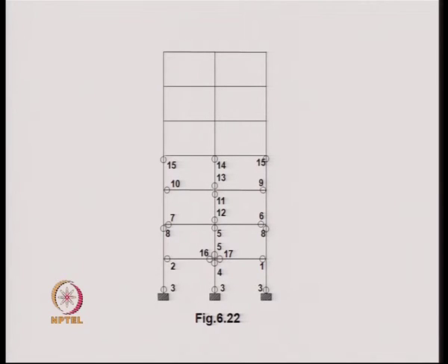So, it depends on the problem. One can continue the incremental displacement up to the state of a desired collapse mechanism, the collapse mechanism that they have assumed, and achieve that collapse mechanism by incrementing the displacement. It may so happen that one may not be able to go up to that state. Before that, a premature collapse state can occur.